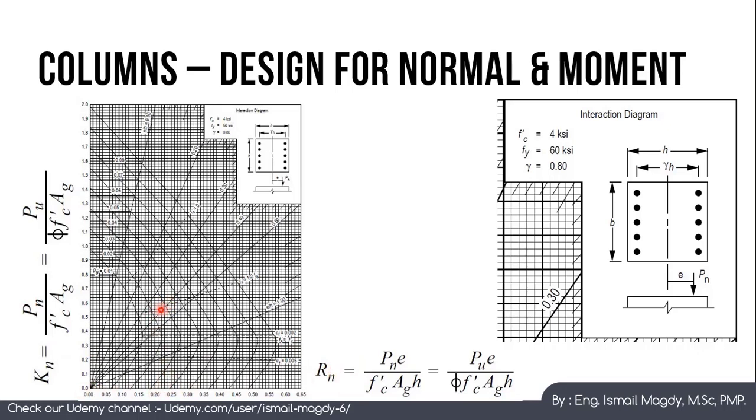Whatever point you choose here, you have these lateral curves. Each one has a percentage of reinforcement, starting from, as you can see, 1%, 2%, 3%. It keeps going up to 8%, which is the maximum reinforcement for a column. And wherever your point falls after you go from vertical and horizontal, this will be the reinforcement percentage required for your column. So let's have an example of this.